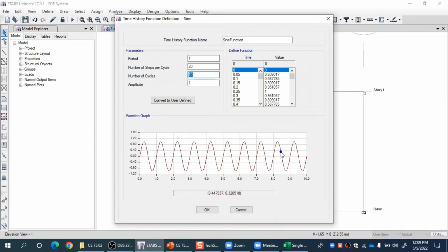But we can change this number also if we want for any other duration. There is a guideline also about that. The loading duration should be sufficient enough to excite all vibration modes of your structure. So if your structure is subjected to sustained loading of harmonic nature, you should perform that analysis for enough number of seconds, so that if your building wants to exhibit the resonance phenomena, it has enough time to develop that resonance response, so that your analysis is technically correct.